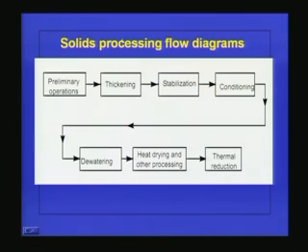Now we will see what process we have to use for solids handling. This is the solids processing flow diagram, because it involves a lot of processes, so I tried to put everything in this single block diagram. The solids flow is coming like this, and initially it goes to the preliminary operations. The preliminary operations consist of grinding, degritting, blending and storage,